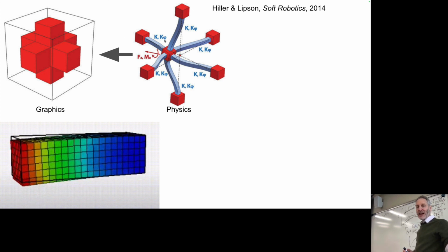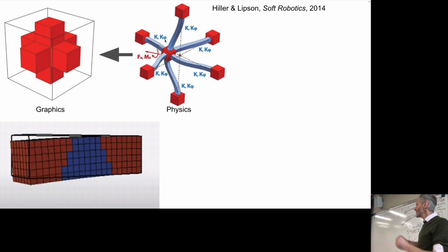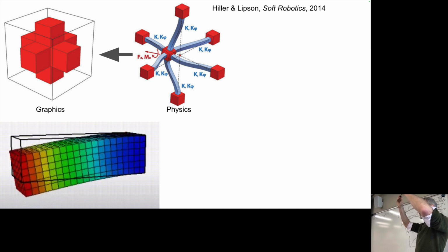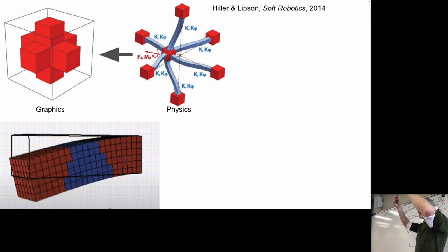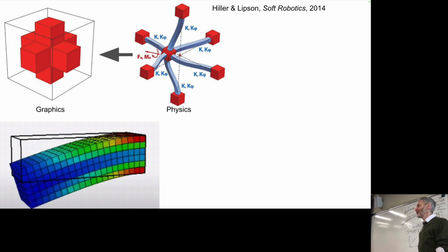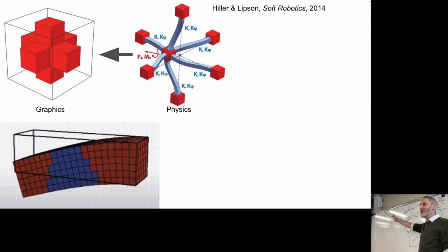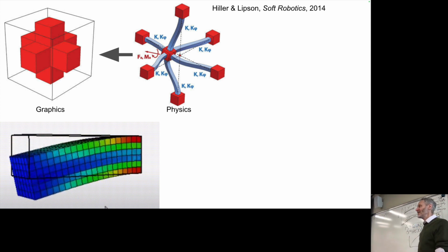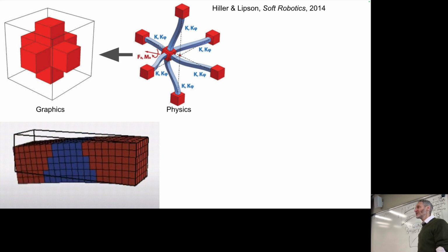The k sub phi here are a second set of three numbers that dictate how that beam or that spring resists yaw, pitch, and roll. The pair of connected cubes twisting or rotating relative to one another. We can set for any one of these beams those 6 numbers to make it more or less resistant to any one or more of those 6 numbers.